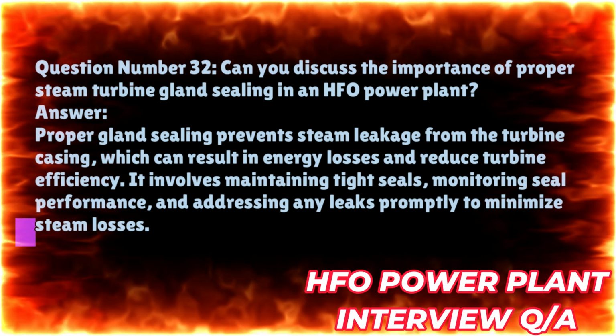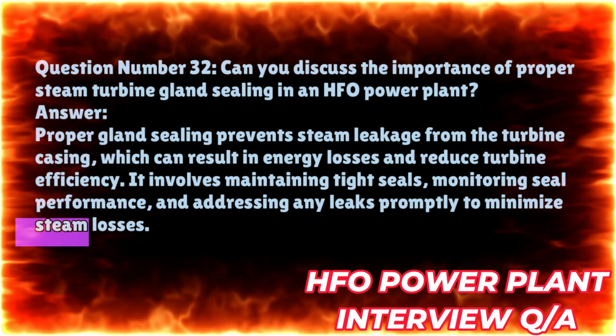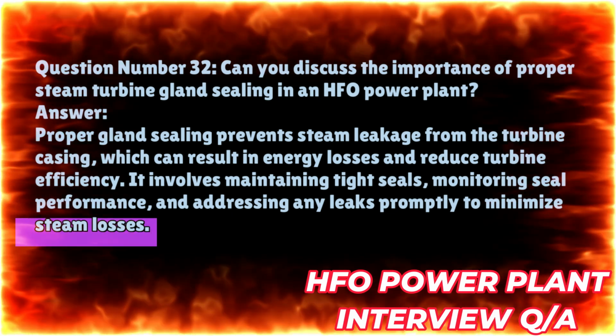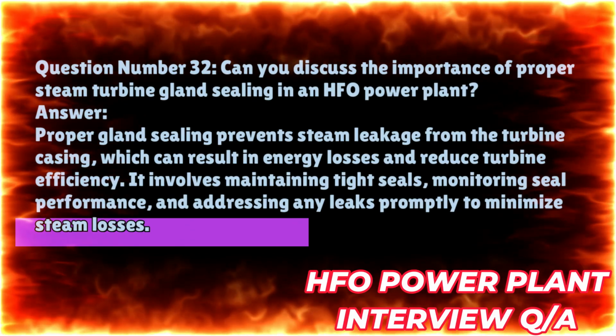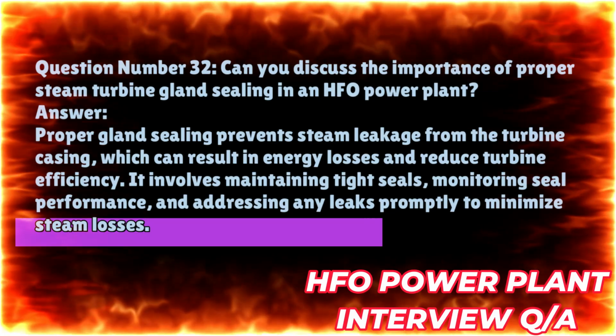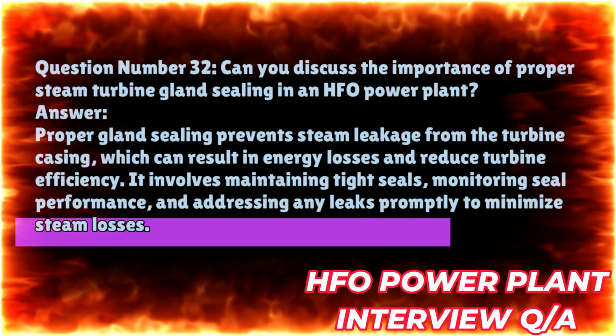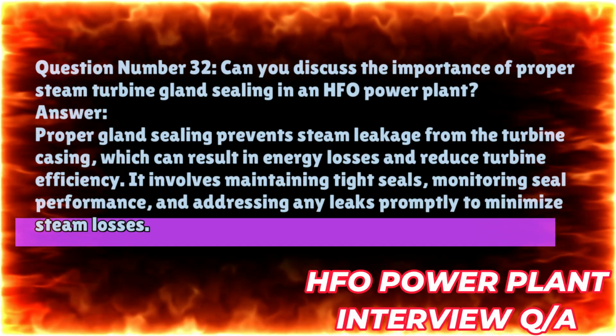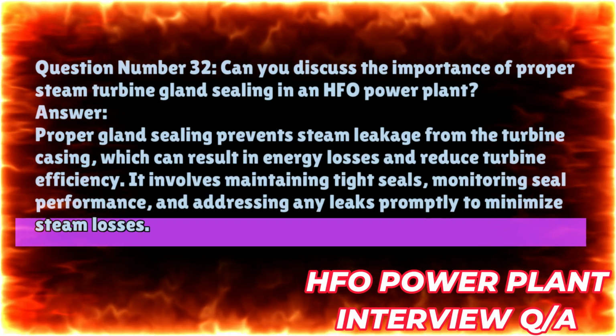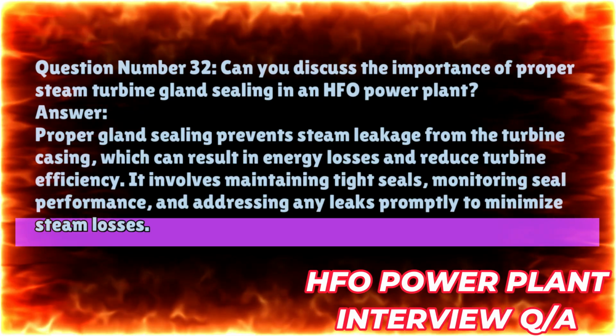Question number 32. Can you discuss the importance of proper steam turbine gland sealing in an HFO power plant? Answer. Proper gland sealing prevents steam leakage from the turbine casing, which can result in energy losses and reduce turbine efficiency. It involves maintaining tight seals, monitoring seal performance, and addressing any leaks promptly to minimize steam losses.